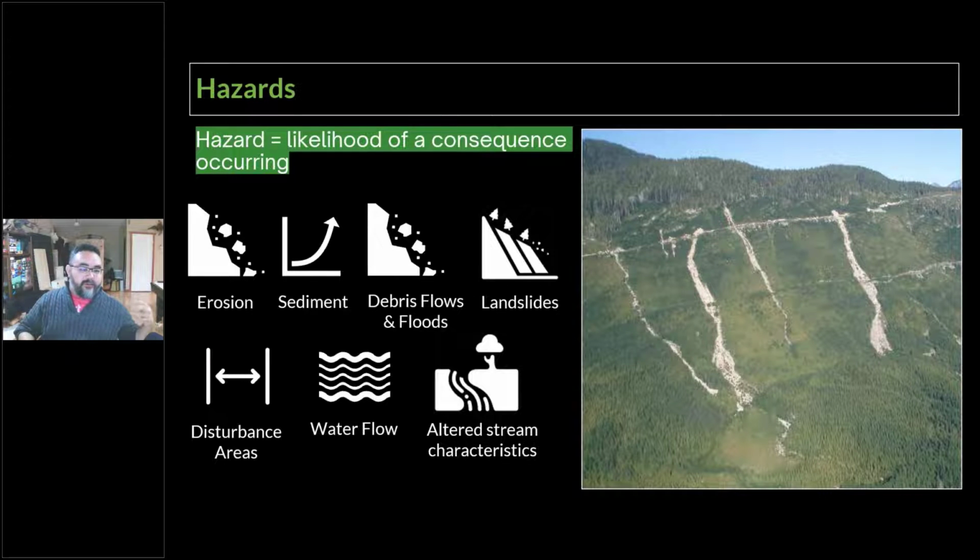And of course, water flow. So we've been talking about debris and debris flows and that sort of thing. But when we divert or concentrate water, we can make other areas wetter and some areas drier. And as soon as we divert those surface flows, we change the velocity, and we'll get into that a little later. But all of these things are going to alter peak flows, so the peak flow of any storm or river flow event.